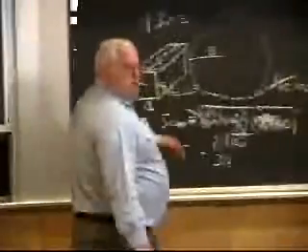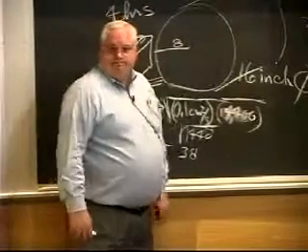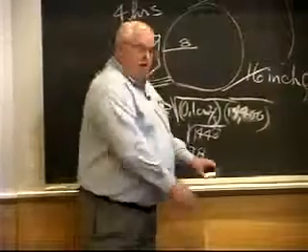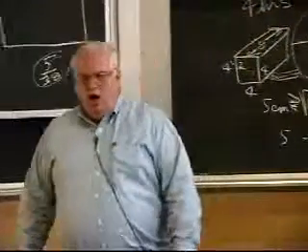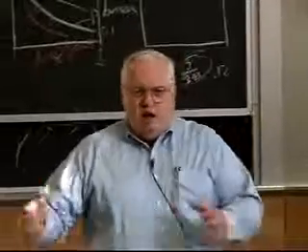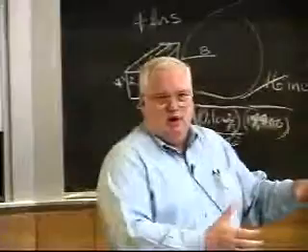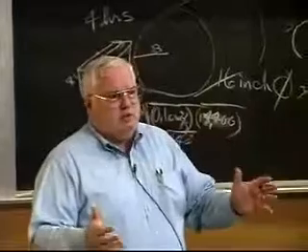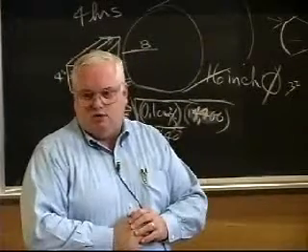So do you think they properly heat treated this thing? No. But they said they did. The steel mill, the heat treater says, oh, we did tests on our furnace, and we found that if you put these into the furnace, and we look at the thermocouples in the furnace, it only takes 3 hours for it to come back up to temperature.